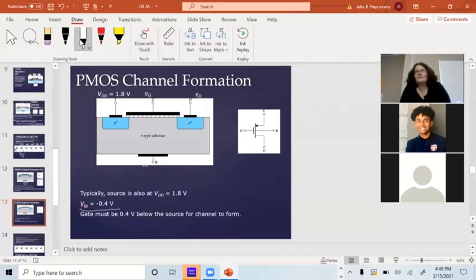The only thing that really changes with the numbers I'm giving you right now is, when you get down to those smaller processes, the 3 nanometer processes, they have to run them at lower power. 0.8 volt logic, 0.6 volt logic. In order to do that, I can't have plus and minus 0.4 of a volt for the threshold voltages.